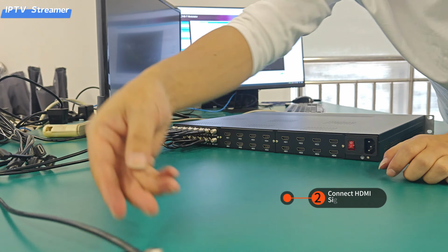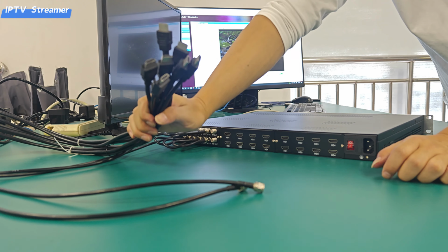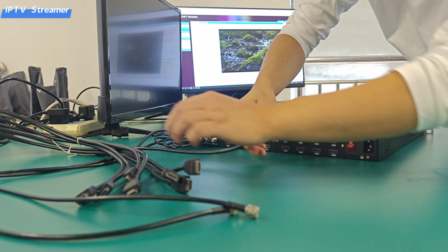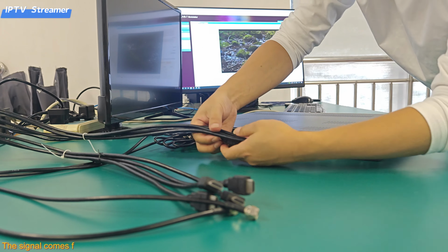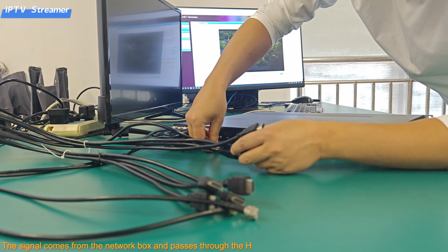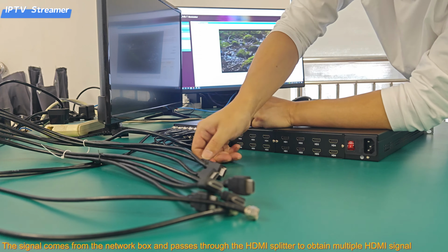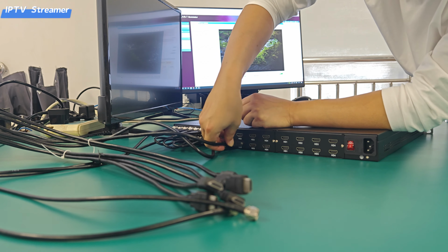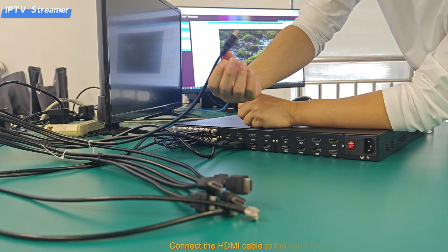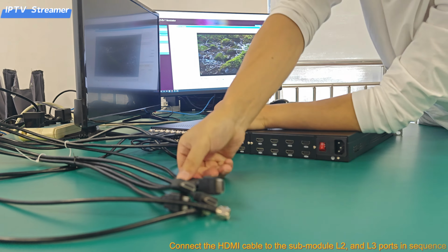Step 2. Connect HDMI signal. The signal comes from the network box and passes through the HDMI splitter to obtain multiple HDMI signal sources. Connect the HDMI cable to the submodule L2 and L3 ports in sequence.